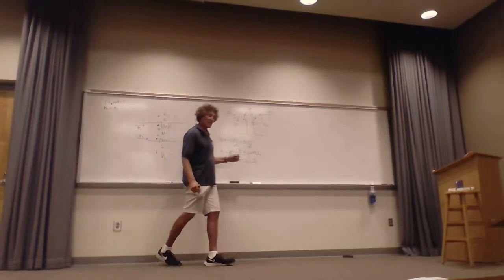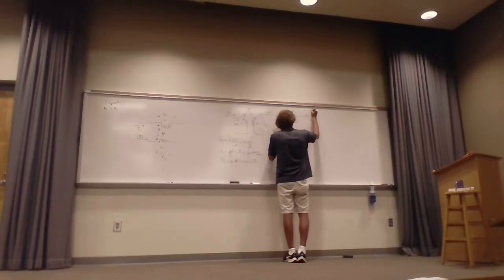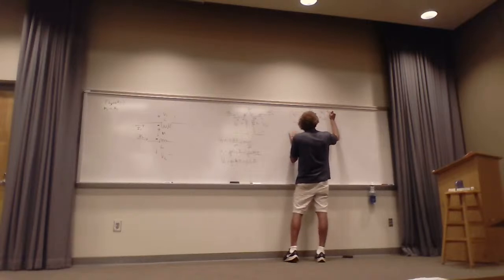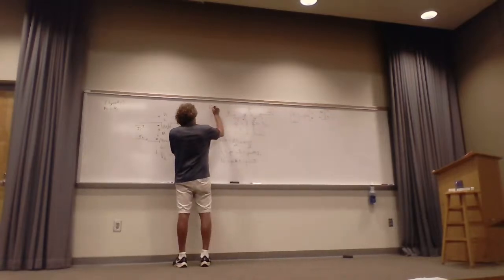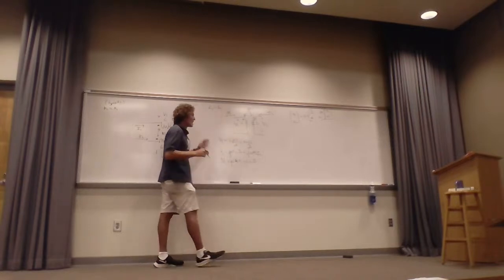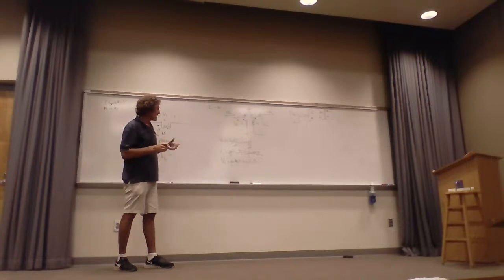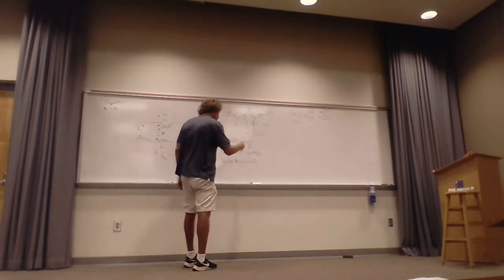And the way I can write that is simply V1, V2 column vector is equal to j omega times the matrix L, M, M, L, times I1, I2. If you look, we'll assume here that L1 is equal to L2. All right. And again, I'm just putting this down here for everybody's sake to see. You've had this.